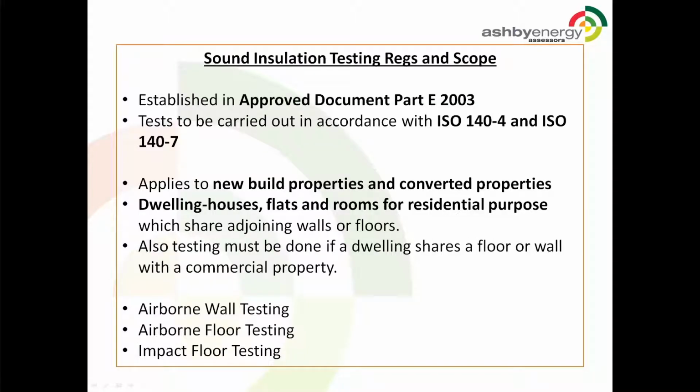Sound insulation testing regs and scope. All testing is to establish compliance with the approved document Part E 2003 of the building regulations. This document details the targets and also offers guidance on the testing methodology. All testing is carried out in accordance with ISO 140-4 and 140-7. These documents can be referred to for specific methodology of each test.